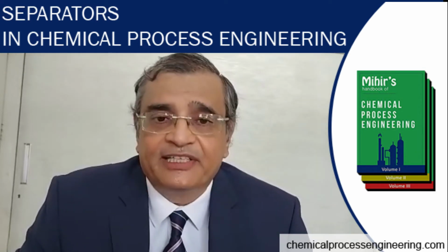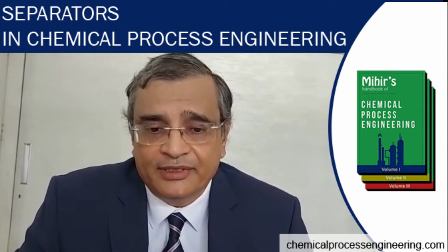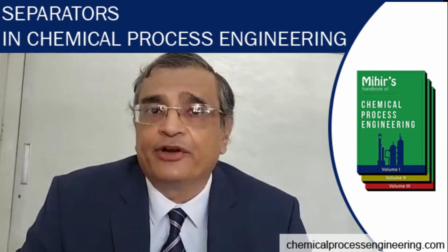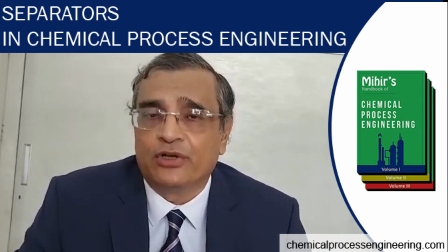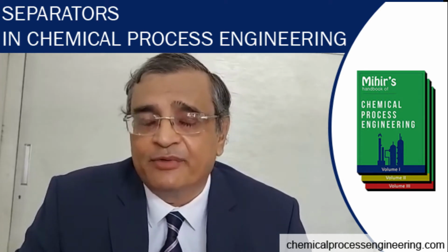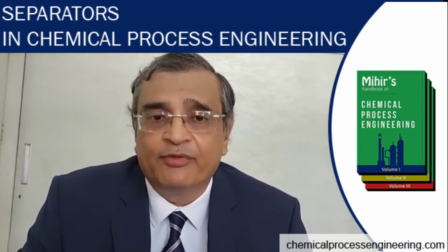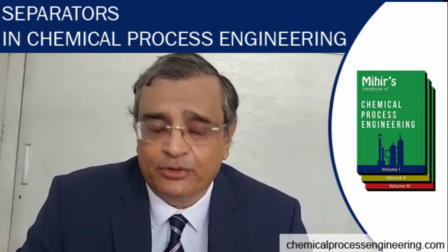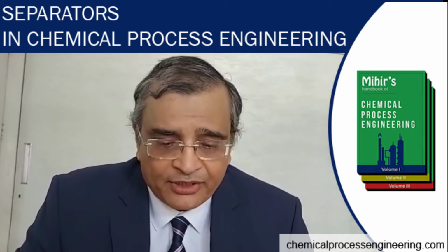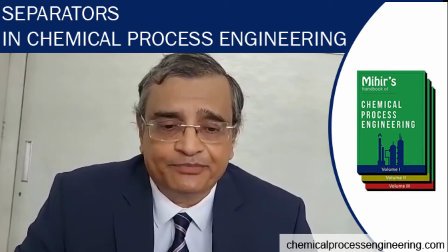In the liquid-liquid separation, you have different laws depending on the Reynolds number. So you have Stokes law, you have the intermediate law, and you have Newton's law. Stokes law where NRe is less than 1, intermediate law for NRe from 1 to 1000, and Newton's law for NRe greater than 1000. So this is how the two-phase and three-phase separators are designed.